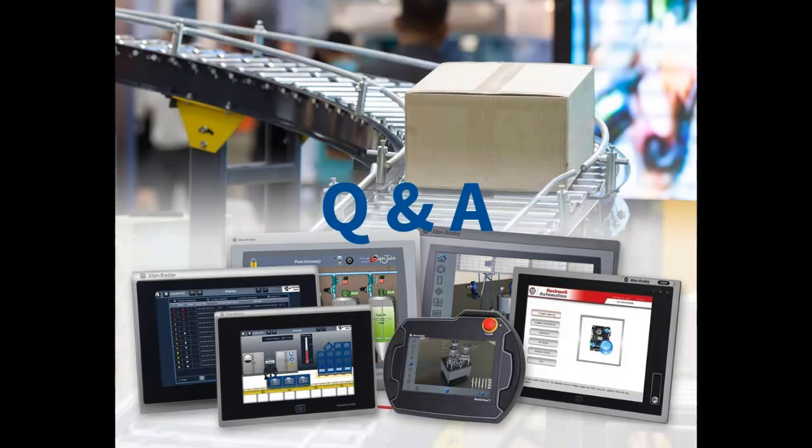That one I do not know off the top of my head. Yeah, I could field that one for you, Derek. So the PlantPAx solution is typically based off of site edition applications, although there are some global objects for ME, but there are no libraries yet for the PanelView 5000. I'm not sure what Rockwell's roadmap is, but nothing available yet.